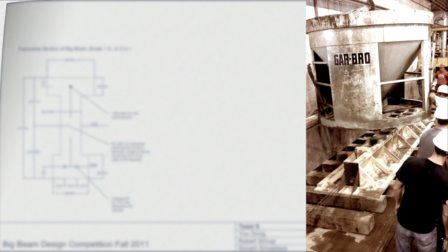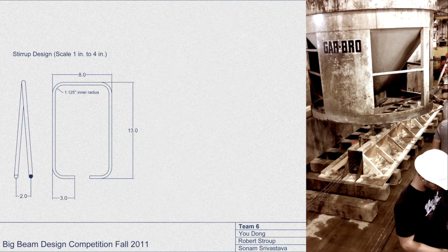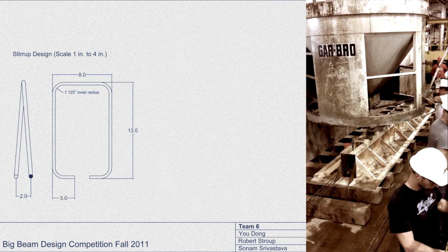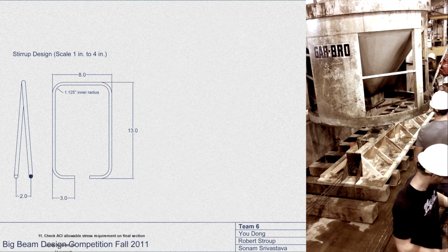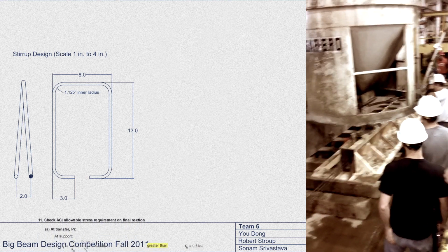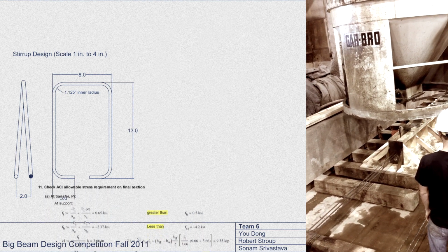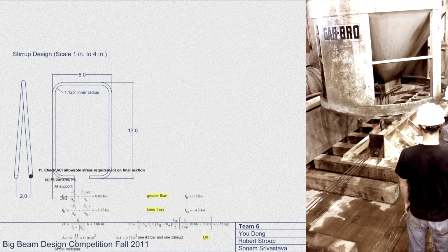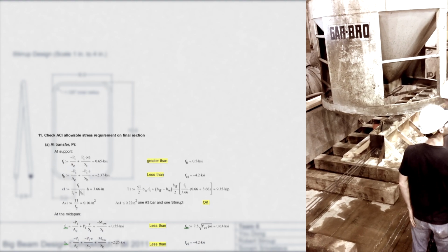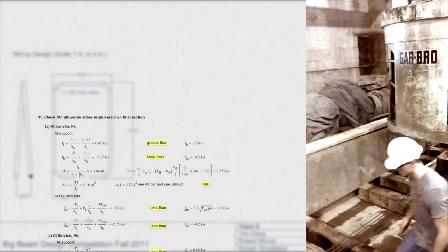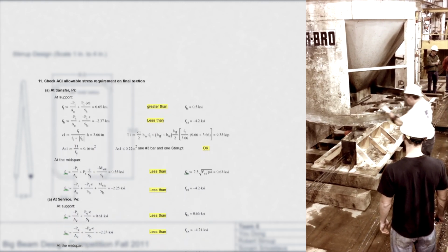Next, we analyzed the required sectional moduli for the different stages in loading. To do this, we added the moments applicable for each stage and divided the summed moments by the allowable stress limits, some of which were multiplied by the reduction factor of 0.95. After we were assured that these values were less than the design sectional moduli values, we then took the latter values and with them determined the overall stress in the concrete. By multiplying this value by the cross-sectional area, we then determined the initial pre-stressing load on the design section. Once the initial pre-stressing load was found, we then determined a required eccentricity of 6.8 inches for the section.